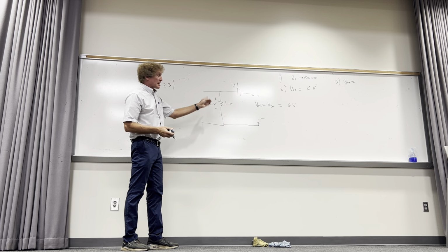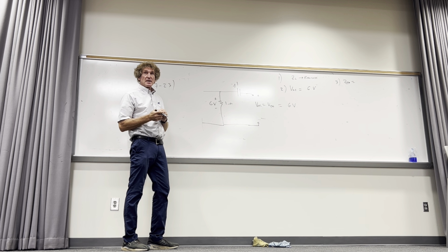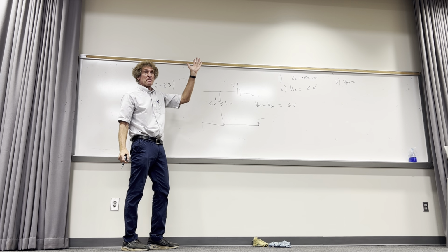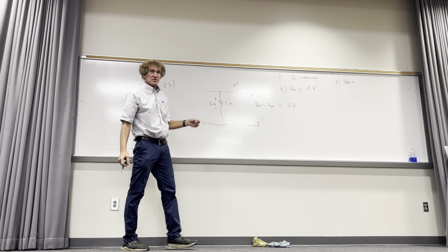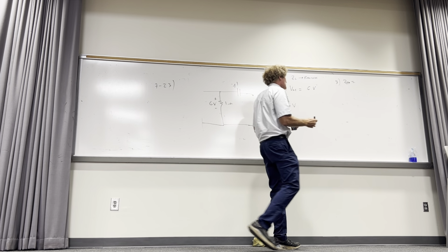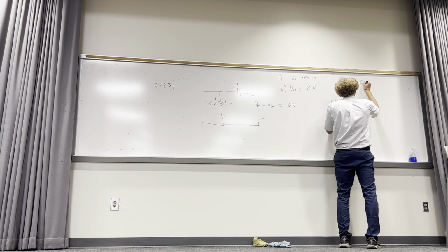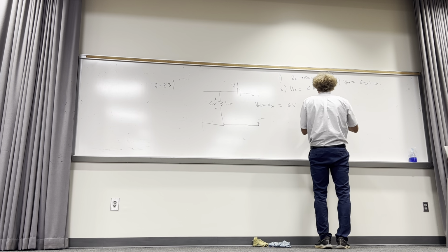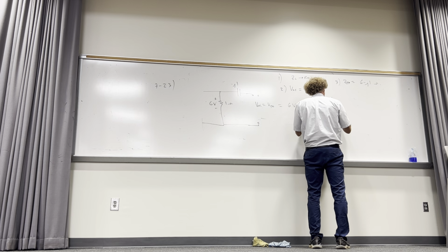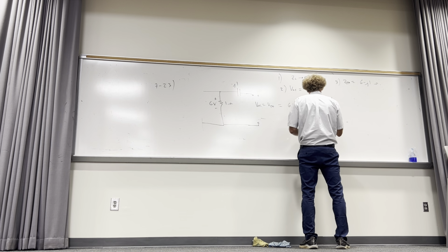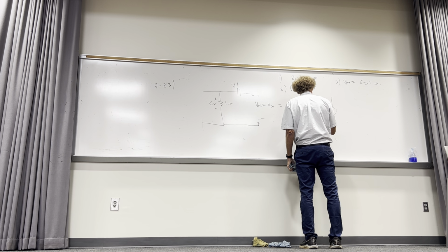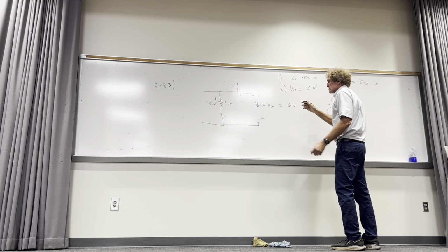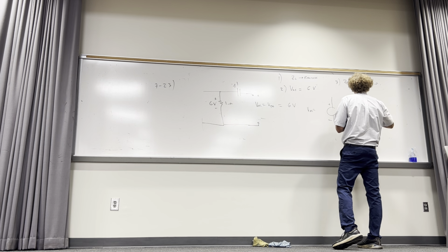Now, just by looking, can you see what the Thevenin equivalent impedance is? It's just going to be 6 minus J1. That's it. So this is simply 6 minus J1 ohms. So now I build the circuit. Here's my open circuit, the open circuit here, which is... Would it be 1 minus J1 since the resistance? Oh, I'm sorry, 1, my bad. Thank you.